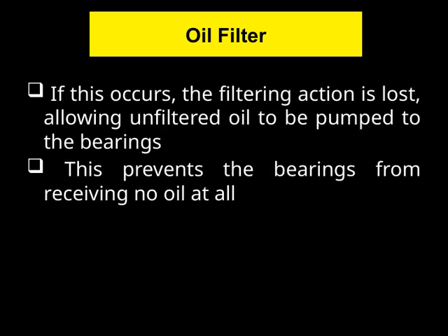If this situation occurs, the filtering action is lost, meaning that unfiltered oil can be pumped directly to the bearings. This is a critical point because it can lead to serious damage. When the filter fails or becomes bypassed, the bearings are no longer protected by the filtering process. This situation at least prevents the bearings from receiving no oil at all, which is a good thing in a way, because complete loss of oil would cause immediate and severe damage.